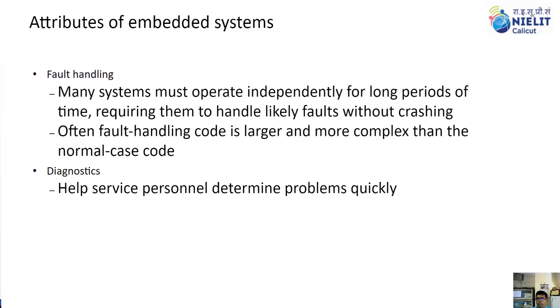Many systems must operate independently for a long time, and require them to handle the likely faults without crashing. So monitoring scenarios are required, and certain applications will be using watchdog timers for detecting these things. So all these facilities should be there inside your embedded system for handling these scenarios.